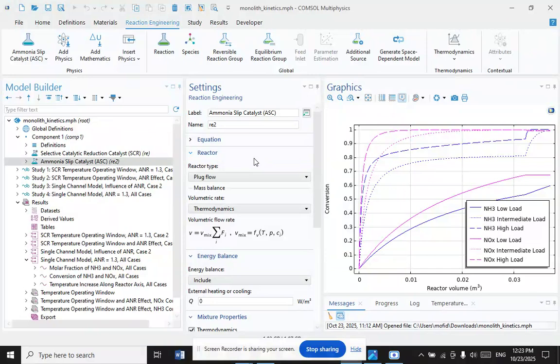The next one is monoliths. The name monoliths stems from the Greek mono and lithos, single and stone. In catalyst reaction engineering, a monolith is defined as a single block of catalyst containing material through which reactants and products are transported by convection.